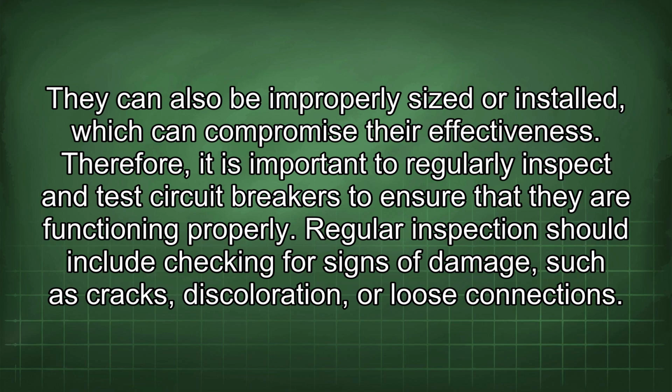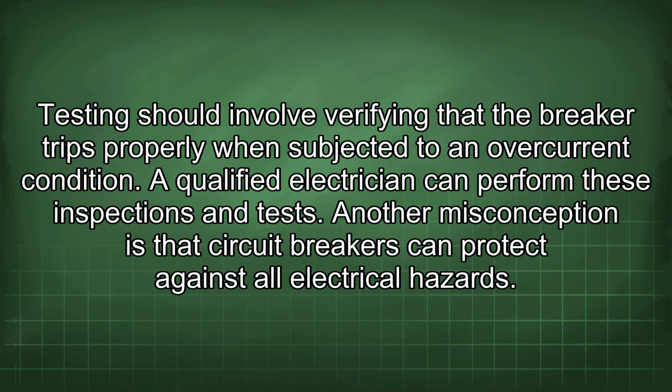Regular inspection should include checking for signs of damage, such as cracks, discoloration, or loose connections. Testing should involve verifying that the breaker trips properly when subjected to an overcurrent condition. A qualified electrician can perform these inspections and tests.